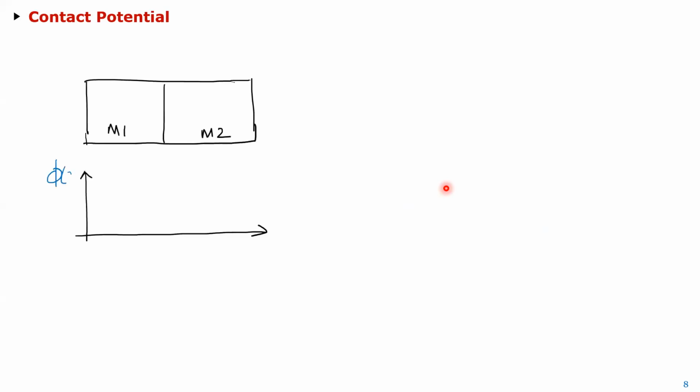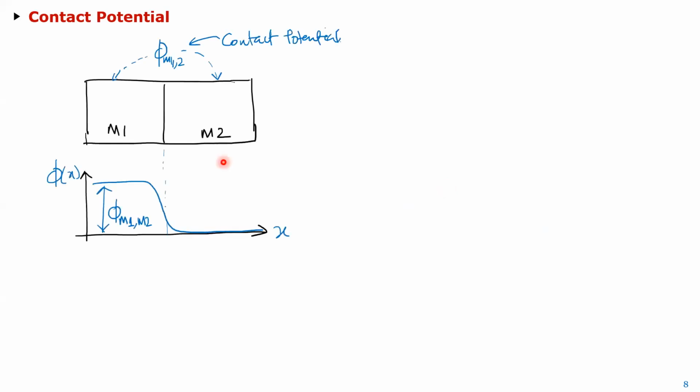Okay, so the last thing on the semiconductor part I wanted to talk about is contact potential. Again, this will be something I'll discuss during the threshold voltage derivation, and I mentioned it last time, so I'll show it again. The contact potential arises if you take any two materials, like metal and semiconductor or metal and insulator.